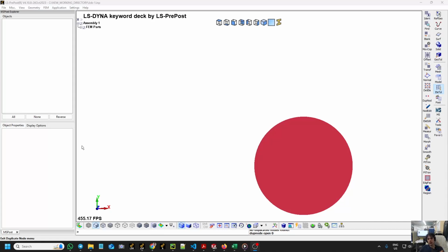And then again after that, we will go to the mesh, but first we need the control part and seed, and then you can choose by number, and then you make sure that you can select the part and mesh that file correctly. After that, you will go to the job and create a job and write the input file. The input file is very important again.